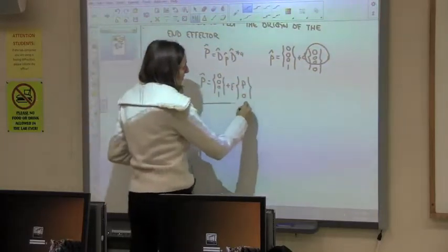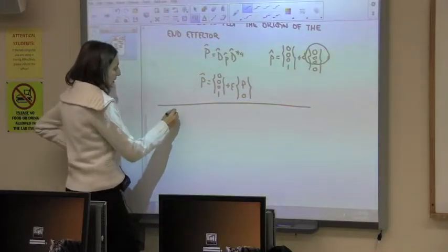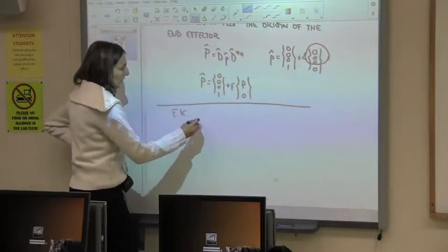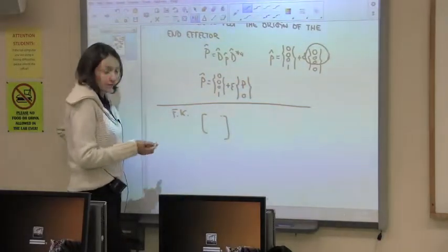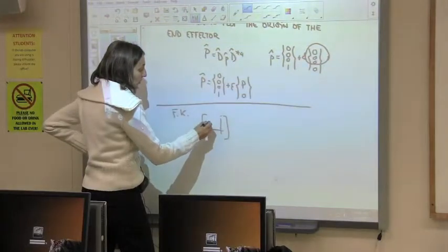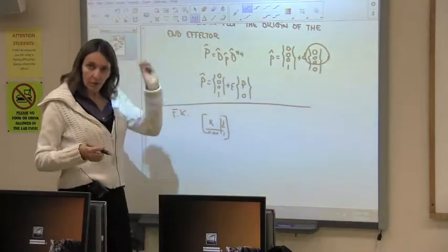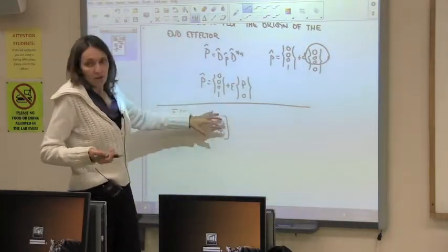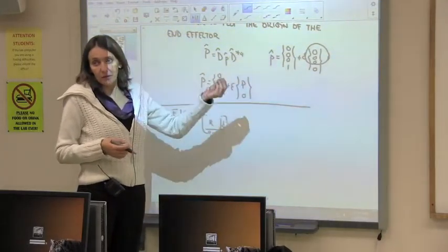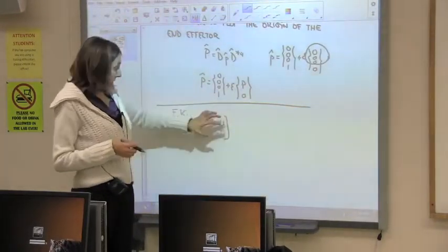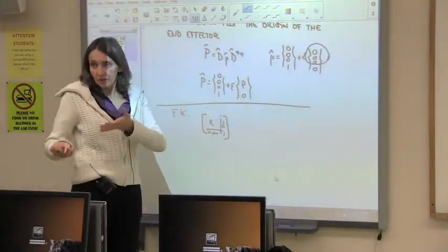So you see, when you do the forward kinematics, let's say the typical one so that you relate to it, you get a matrix. That's not a point, that's a displacement. It has a rotation and a translation part. Now you can take this matrix and apply it to any point, and then you get a point on the workspace. But you can argue that this is the workspace of displacements, and the other will be the workspace of points. Once you have the workspace of displacements, then you apply it to any point, and you get the workspace of points.